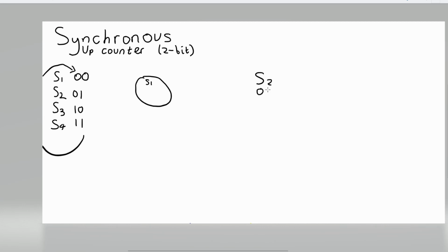If you just wanted to count between those two, you would do like that, which is useful for some applications because you can manipulate a synchronous D-type circuit to get whatever output you want in a sequence with a sequence generator. So let's just draw the state diagram.